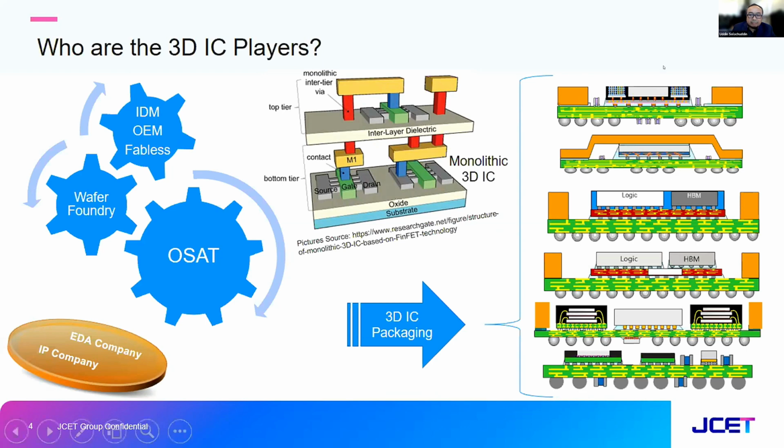So for OSAT, like what the previous speaker mentioned, this kind of heterogeneous packaging falls into so many flavors, so many options in the business, that between OSATs there's very high competition in the technology offering, from multi-chip module with laminate, or with substrate, interposer, or even with fan-out solution. Some call it system in package also, as a general offering, including 2.5D or 3D itself with stacking or the inclusion of a microprocessor and HBM. Those are the normal portfolio offered by OSAT.